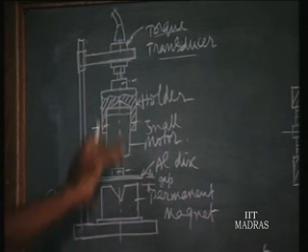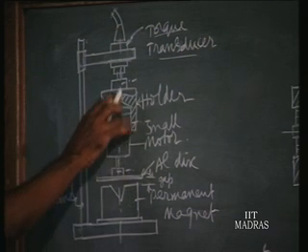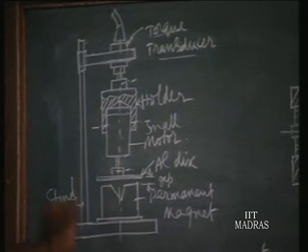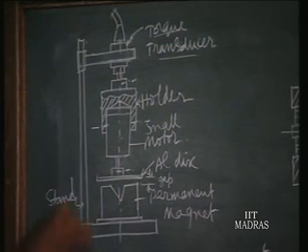So here essentially we are measuring the torque by the reaction principle. In the rotor, the torque is developed. The reaction is taken by the reaction torque available in the motor stator, which is taken up by the transducer and given as voltage.